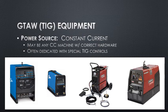All right, let's talk about TIG power sources. As we discussed earlier, they are constant current machines. When you walk up to the front of the machine, you're going to set the current, and then you might use a remote control to control your amperage during the weld. This could be any constant current machine, including an engine drive, a stick welding machine, or any other machine that produces constant current output, as long as you have the right hardware to go along with it, which would include your gas valves, torches, and things like that.